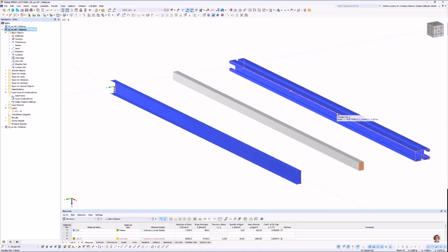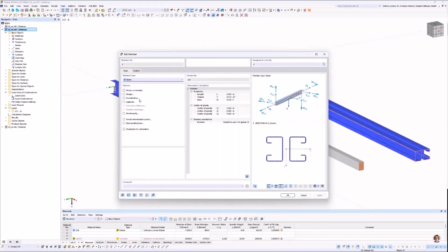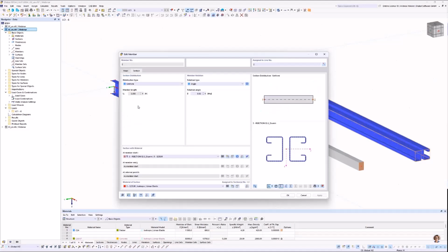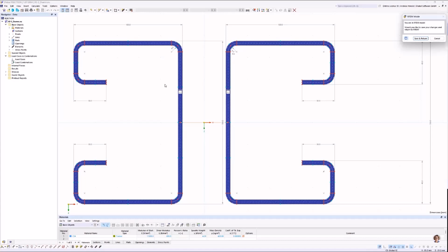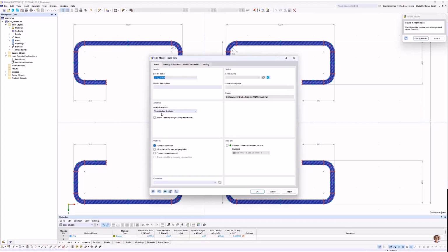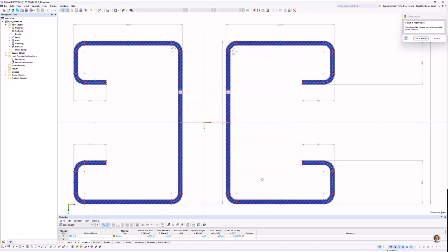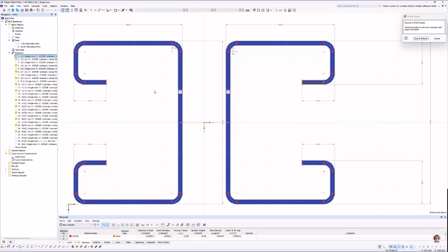So I double click on the member on the right side. Section, also a section that was created in RSECTION. I press the button again to turn to RSECTION. So I turn to the base data again, left above, and you can see thin-wall analysis is checked. Okay, and also parts and elements must be defined.